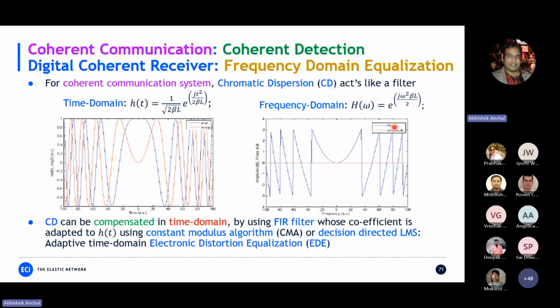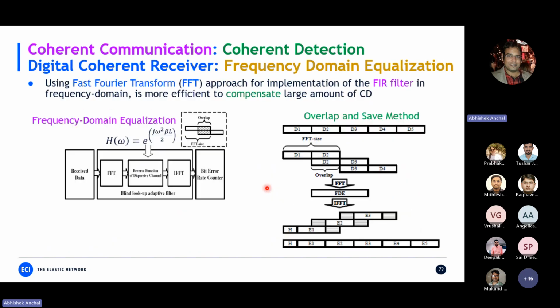And when the signal passes through this electrical filter, which is opposite of the dispersion, it compensates the dispersion. So there are many algorithms used to compensate the dispersion. Basically, what I'm saying is that we will create a filter whose profile is opposite to the dispersion the signal is facing in the fiber. That way it compensates and you reduce the dispersion in DSP.